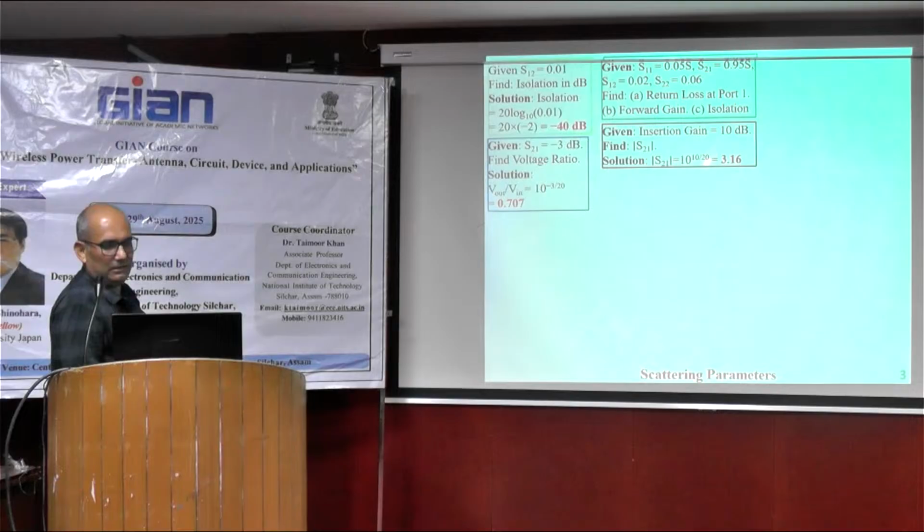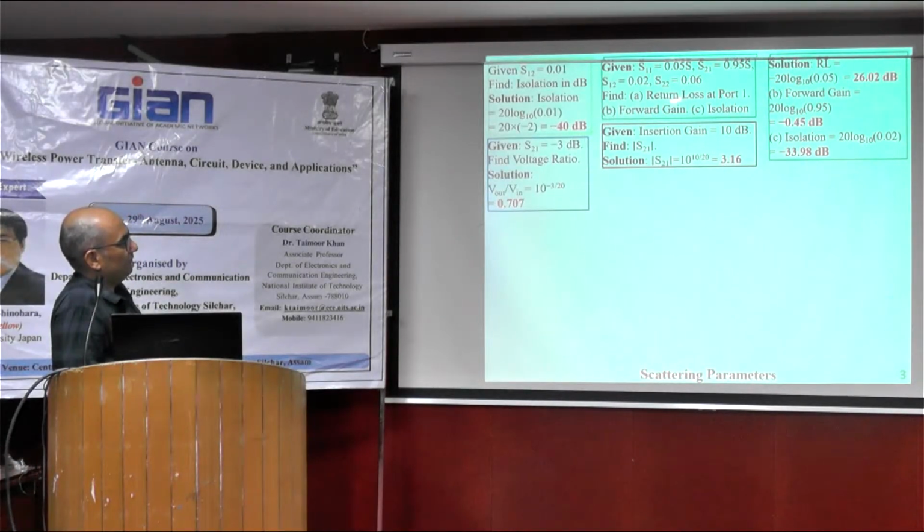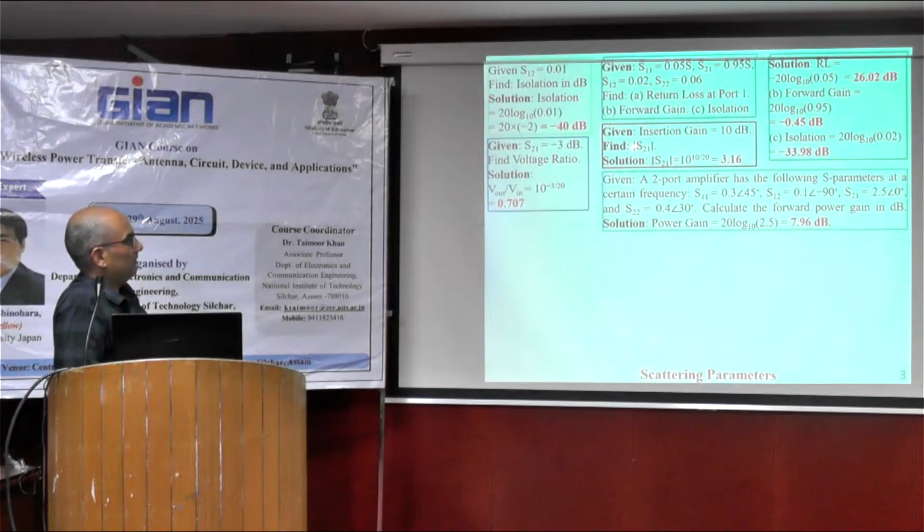Then insertion gain, then the solution for this first part is this one. Okay, for this part it is S21. Where is S21? Where is the solution of this one? Oh yes, S21 equal to 10 to the power 10 upon 20, that is 3.16.